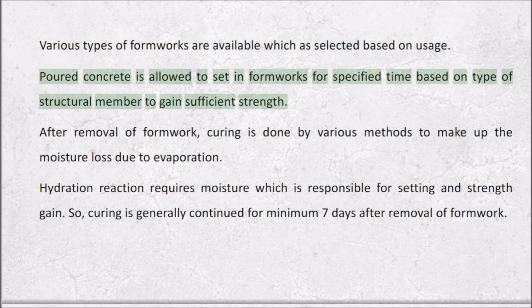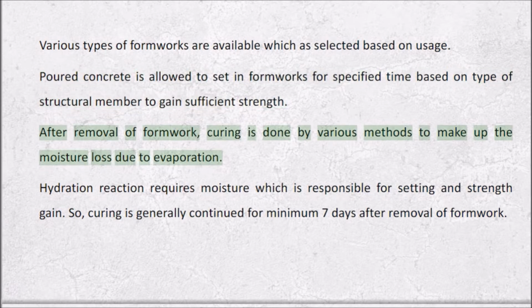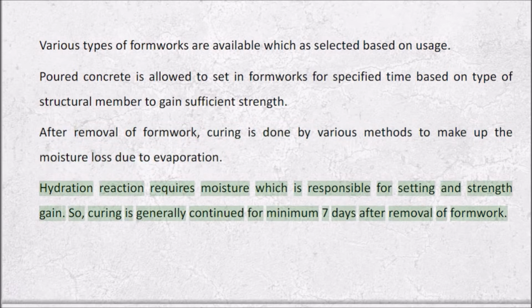Poured concrete is allowed to set in formworks for specified time based on type of structural member to gain sufficient strength. After removal of formwork, curing is done by various methods to make up the moisture loss due to evaporation. Hydration reaction requires moisture, which is responsible for setting and strength gain. So, curing is generally continued for minimum 7 days after removal of formwork.